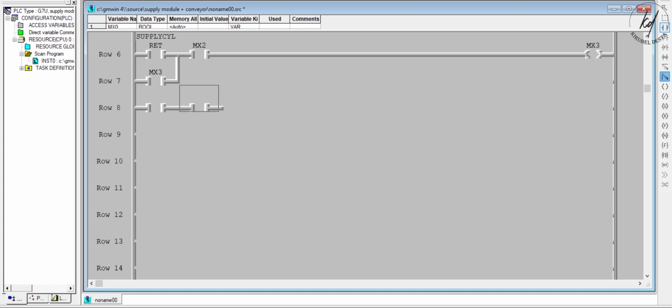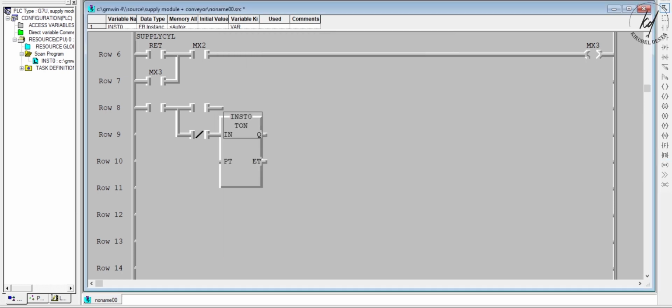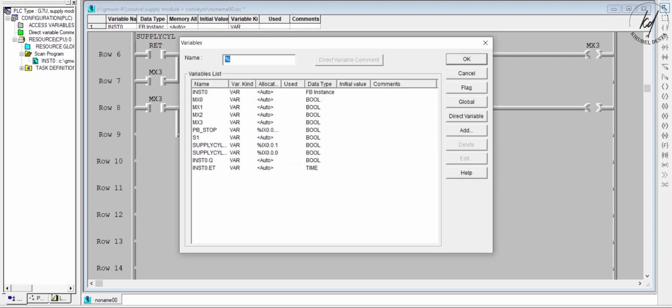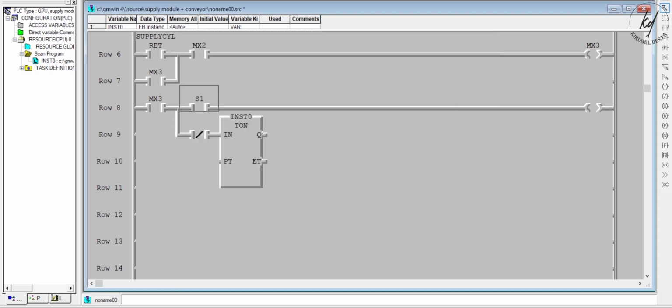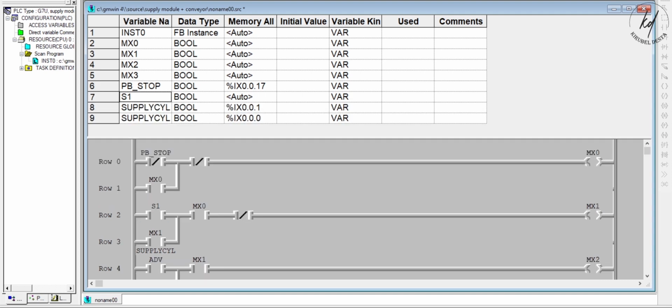Pneumatic processes sequence, PPS, is used widely in industrial applications. It is common to do a predetermined PPS to achieve a specific larger task within the industrial application. A PLC-based PPS control system is designed and implemented, in which the PPS is programmed by demonstration. The PPS could be changed by the user demonstrating the new required sequence by following a simple series of manual steps without having to change the PLC's original program, which leads to decreasing the cost and time.